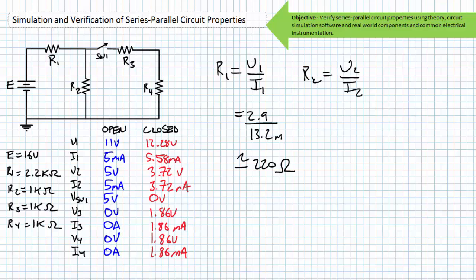No wonder current was so high. No wonder V1 was proportionately so low. No wonder V2 was proportionally so high. A quick check of the 4-band resistor color code would indicate a brown third band on resistor R1. A quick swat to the back of your lab partner's head and a supervised second visit to the stockroom to get a 2.2 kiloohm resistor with a 4-band color code of red, red, red, gold should rectify the problem.